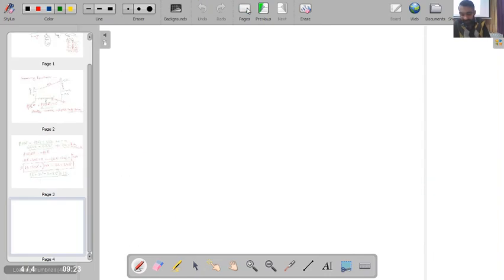So for energy equation, what will be happening? Can you tell me? So if I take the steady condition, then I will remove the time term. So I will consider the second term of the energy equation, which is rho V vector dot dS vector. This makes my mass advection, and along with this some energy will be going, that is U plus V square by 2.